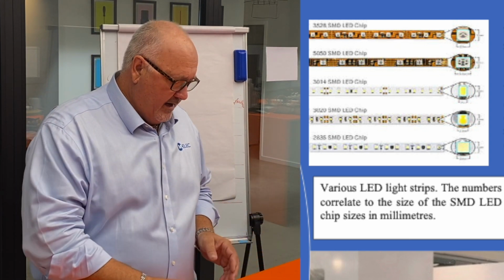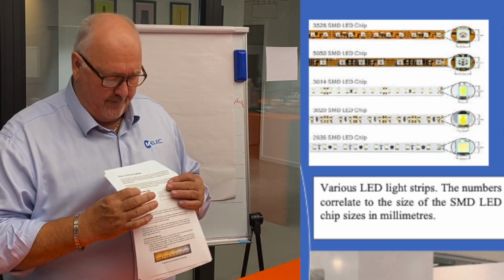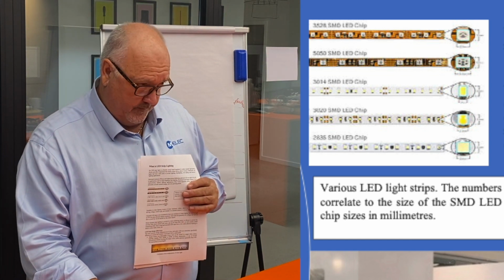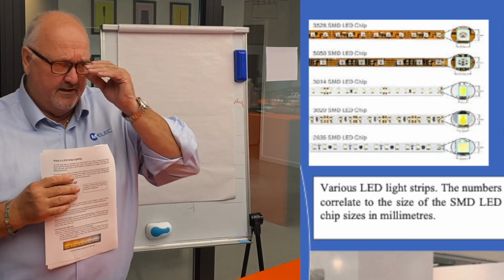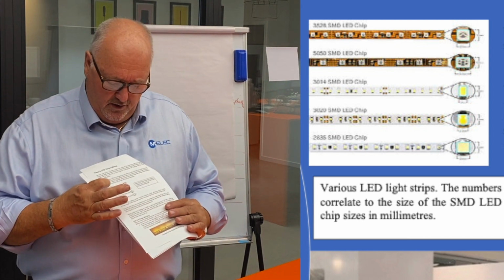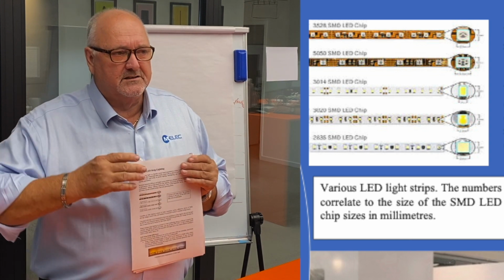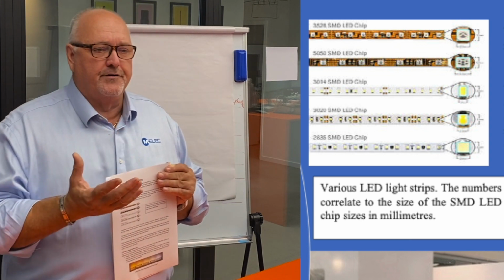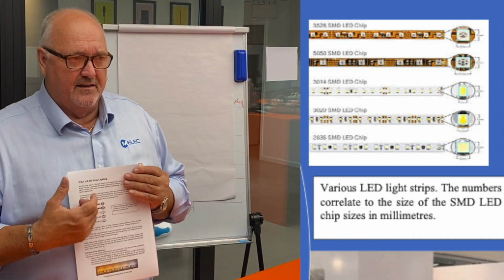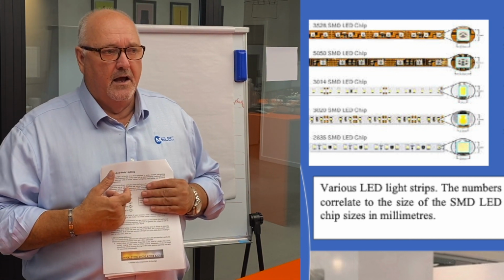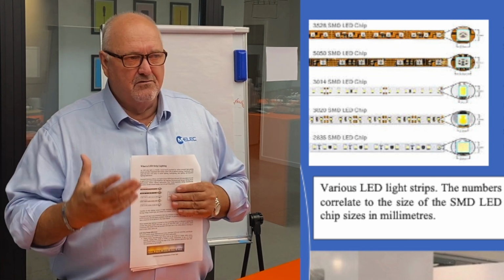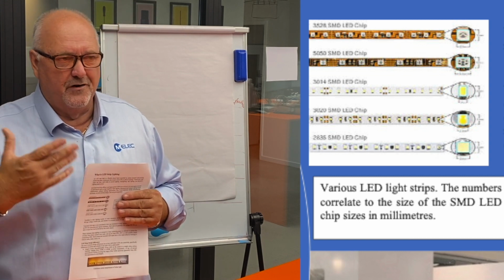Now, the brown, and we don't have a very good picture of it just here, which we can see at the top of your PowerPoint presentation, is what we would class as being open, it's uncoated. So if you were to scratch that, you could damage the LED, the actual printed circuit board, straight away. Because it's uncoated, it has no resistance to any kind of water if it gets splashed.